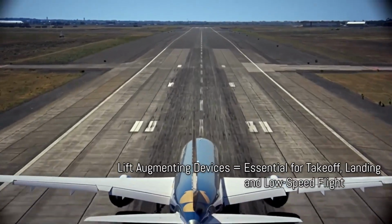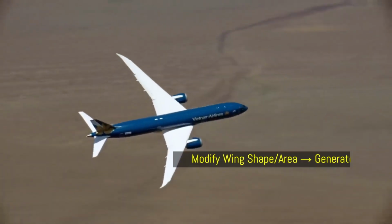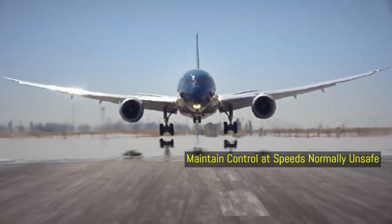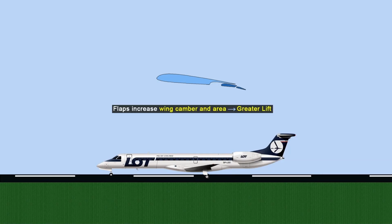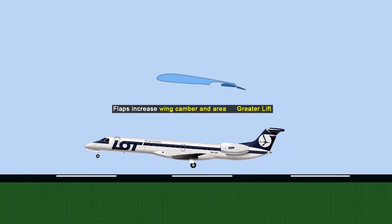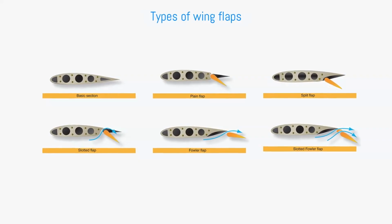Lift-augmenting devices are critical for safe takeoff, landing, and low-speed maneuvering. By changing the wing's shape or surface area, they help the aircraft generate more lift and maintain control at airspeeds that would normally be unsafe. The most common lift-augmenting surfaces are the flaps, located along the trailing edge of the wing. When extended, flaps increase both the camber and the area of the wing, producing greater lift. This allows an aircraft to lift off at a lower speed during takeoff and to slow down more effectively during landing.